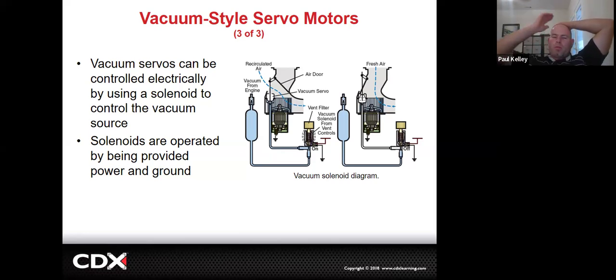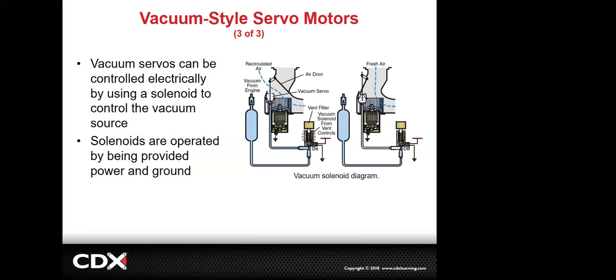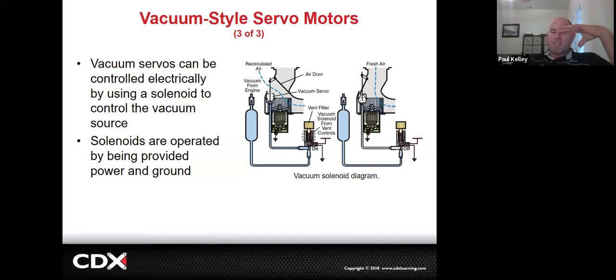When you go wide open throttle, does anyone know what happens to your manifold vacuum from when we talked about vacuum boosters? You lose some vacuum, right? Or the vacuum goes down. Yeah, if you're full wide open, you'll probably have zero vacuum. So if you have zero vacuum, how is this supposed to hold it in position on a vacuum actuator? Think about that.